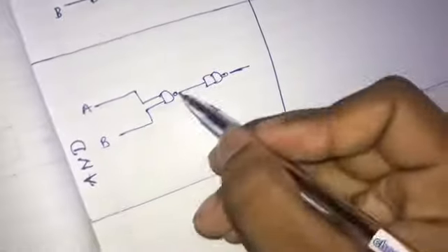simple as that. Okay, so when it comes through here it will be AB bar, right? So when it goes through this again, so the other thing is the NOT gate, right? That's one of the most important things when it comes to this. It's anything you send it through the same thing, right? So if it's A, when you send it through NAND by itself, it turns into A bar, right?